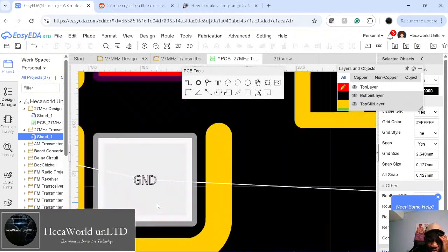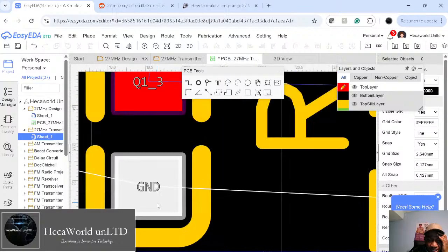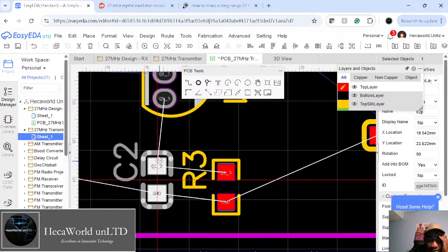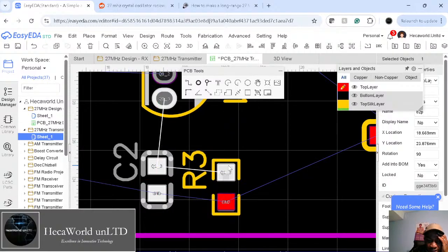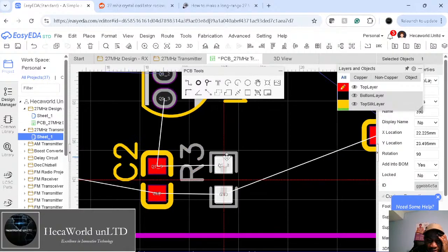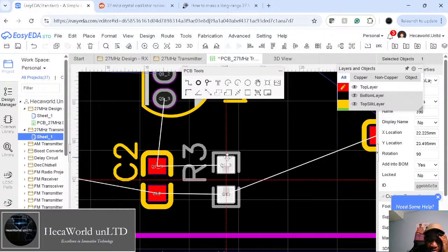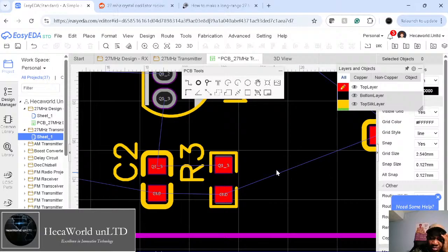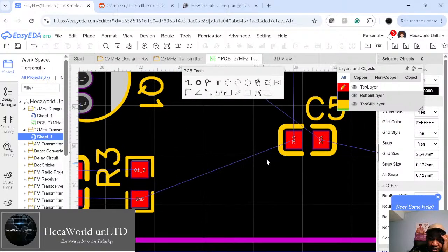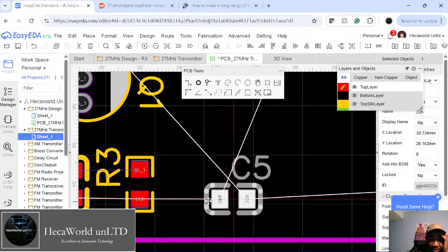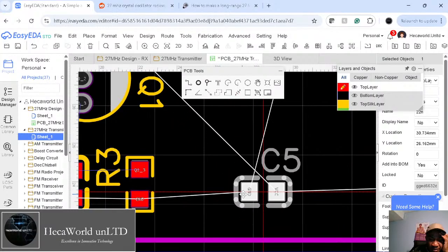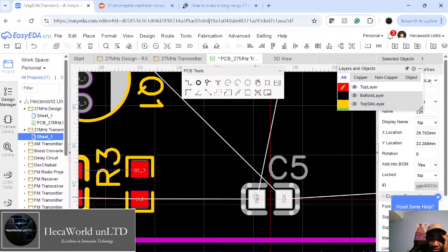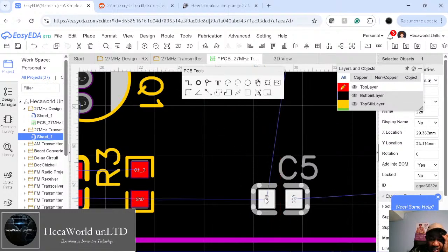Normally, I will zoom in and make sure that the components are aligned. Like I can make this to be at the top of the line that way, and then this one also. But this is just based on your own perfection, the way you want it to be, right? So sometimes I make sure these are aligned so that my traces, once I start running trace on a particular line, they will just run on a straight line as much as possible.